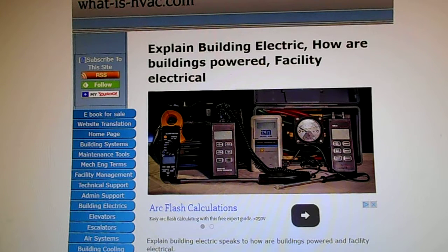Electric supply to substation. Electricity distribution to the substation occurs before the electricity is delivered to the end users or facilities of all kinds. This electricity is considered as medium voltage systems, which are 50 kV lines or lower to transmit to power lines, electrical substations, pole-mounted transformers, low voltage wiring, which is less than 1 kilovolt, and to electrical meters.